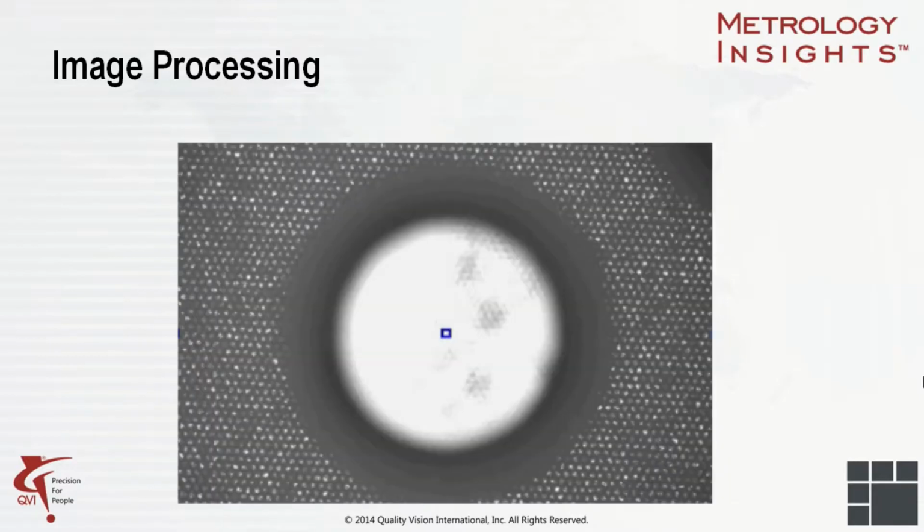In this scene, we see a frequent problem in optical measurement. The surface of this metal part is very shiny, so shiny that all the light reflects off it and we can't focus it sharply. A similar problem occurs when we try to focus on translucent materials. The light passes through the surface, so we can't see it clearly. In order to focus on areas like these that have no natural contrast, we can project an image of artificial contrast onto the surface to give it the appearance of texture. The checkerboard grid pattern is focused exactly at the focal length of the optics. The grid appears sharply focused when the part surface is in focus.